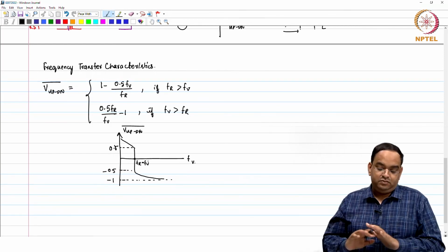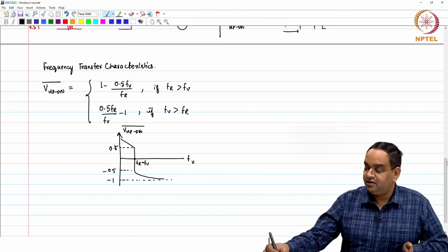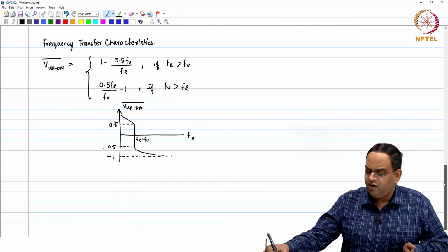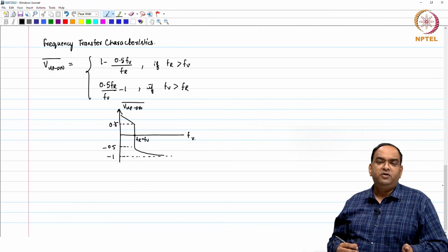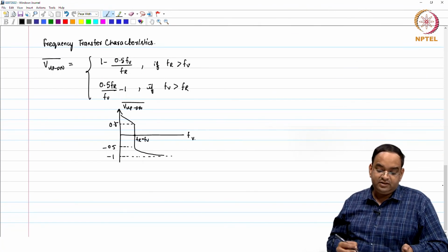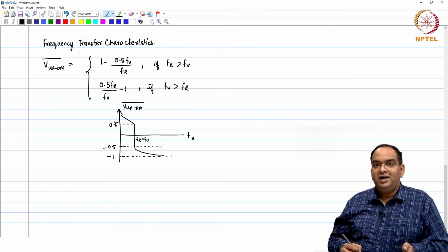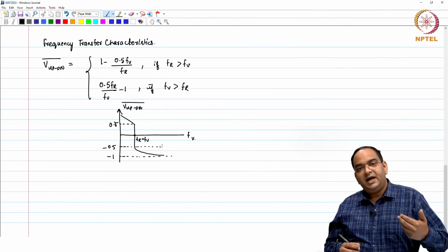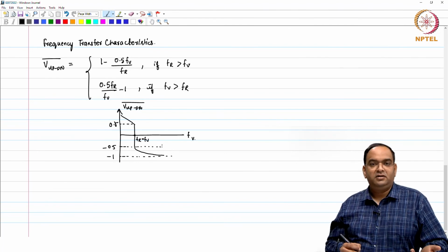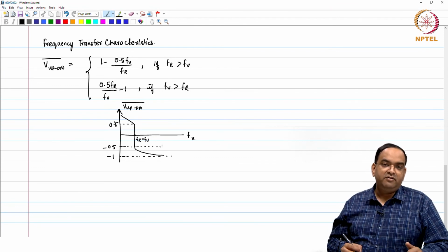Okay. So, this transfer characteristic you may not use in your PLL. The only thing it is telling you is that if I use this PFD, I will detect the sign of the frequency error correctly. I will apply the correct change to the VCO's frequency all the time, and I will acquire the frequency locking also. Okay.